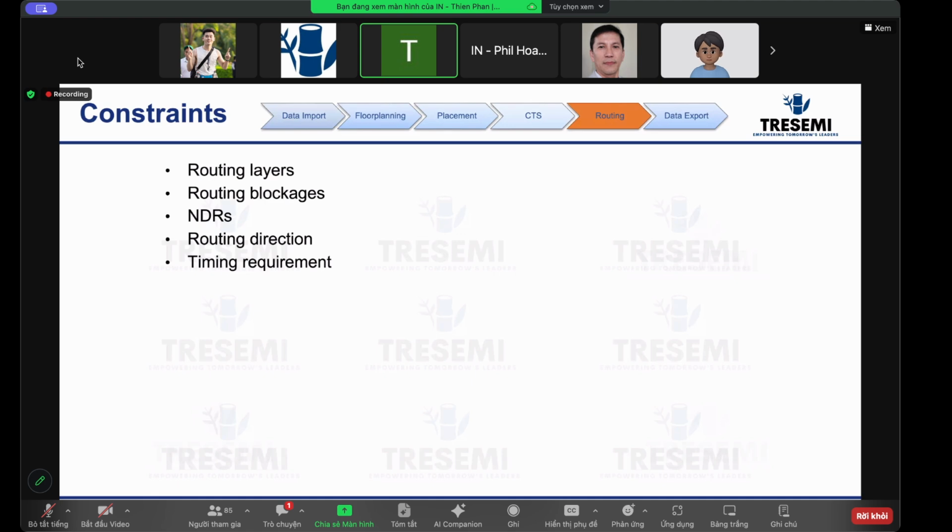We can route that net on certain layers with a certain width and with certain spacing to the neighbor, right? Or even we can add shielding, right, on the sides or top and bottom. So those are the options that we can play with, right? So usually those special cases we want to do upfront, right?